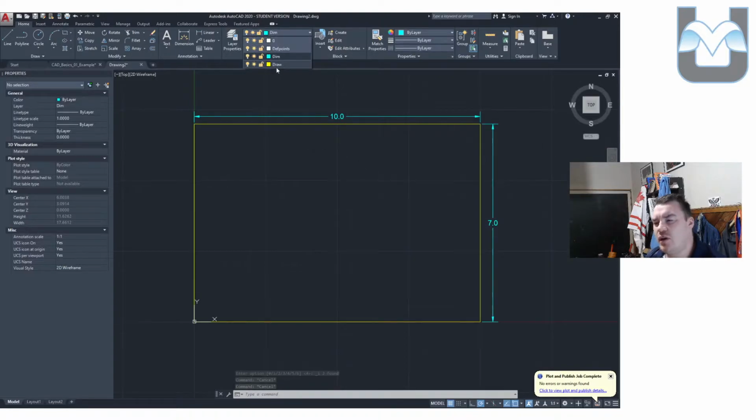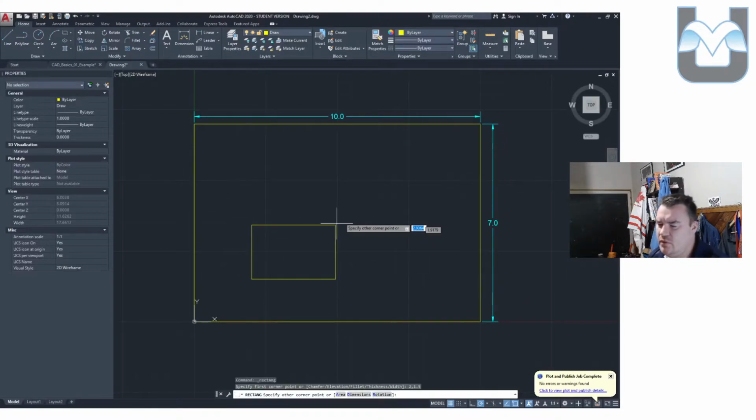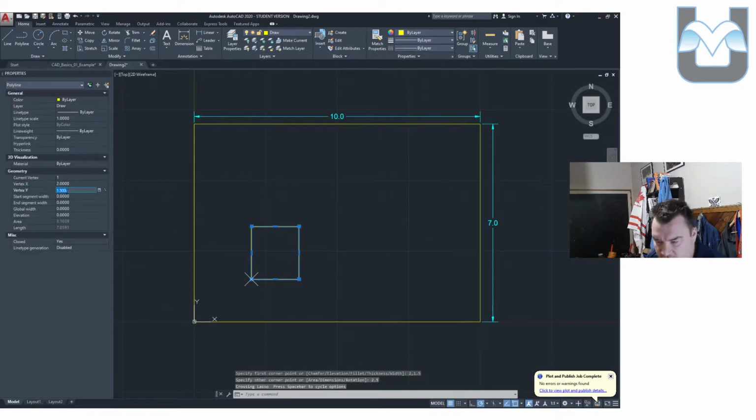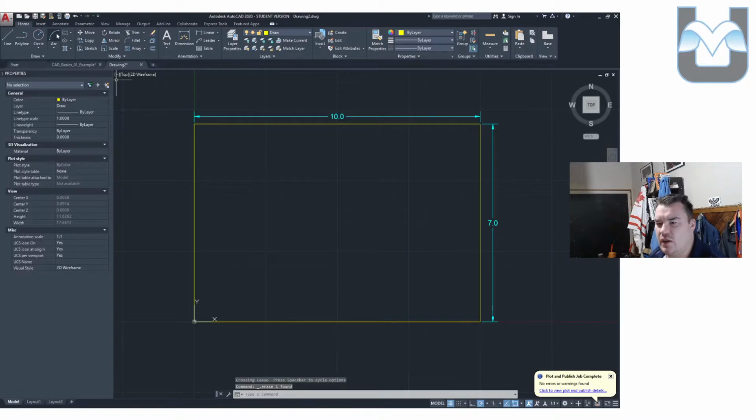Now I'm just going to quickly draw all of the things that I know I have an existing coordinate point for on this drawing, which is this square here. Obviously I drew the side of that wrong. I'm going to see if I can change the side in the properties menu. I indeed cannot. Okay, that's interesting. Let's delete that and try that again. I'll just draw the rectangle. We'll start it again at 2, 1.5 like the drawing suggests, and 2.5, 2.5. There we go.